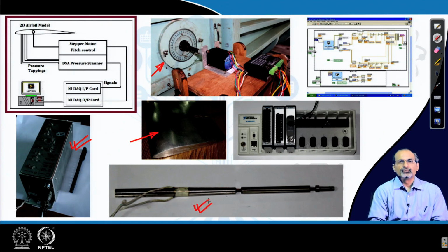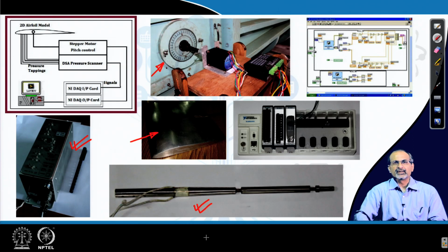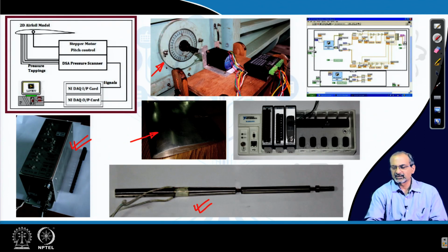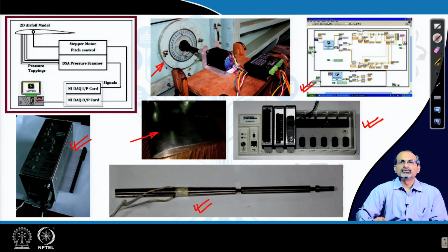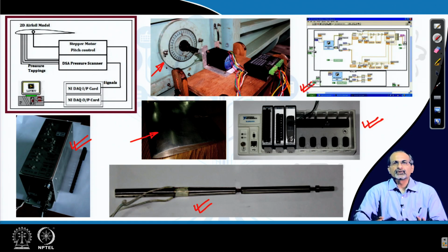Similar is the case with a sting balance, which has the capability of sensing forces acting on a wind tunnel model and converting them into electrical signals. Those electrical signals are fed into certain data cards, and then they are further ported into the computer, where you have software which can handle the data, and then you can post process the data using that software appropriately, so that you can do the necessary calculations.